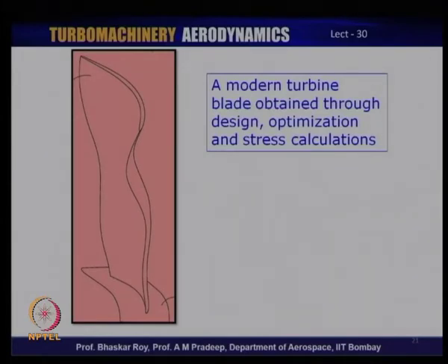What we have seen now is that the turbine blade creation requires a lot of empirical correlations, lot of use of computational fluid dynamics, also optimization with the stress calculation. What I have not mentioned is, in case of low pressure turbines, is not only stress calculation, but aeroelastic calculation needs to be done. That means, that allows you to calculate the blade vibrations. All of it together finally gives you the axial flow turbine blade. That brings us to the end of axial flow turbine chapter.